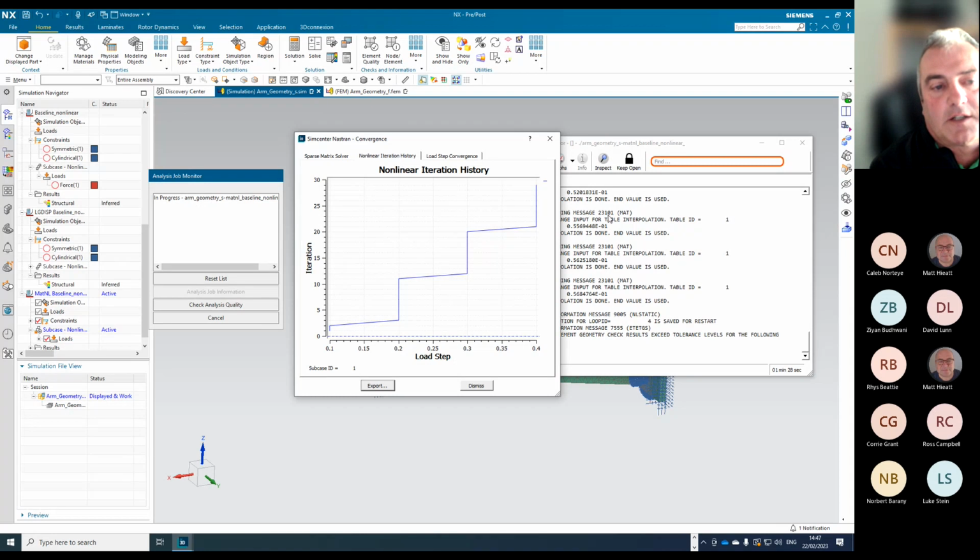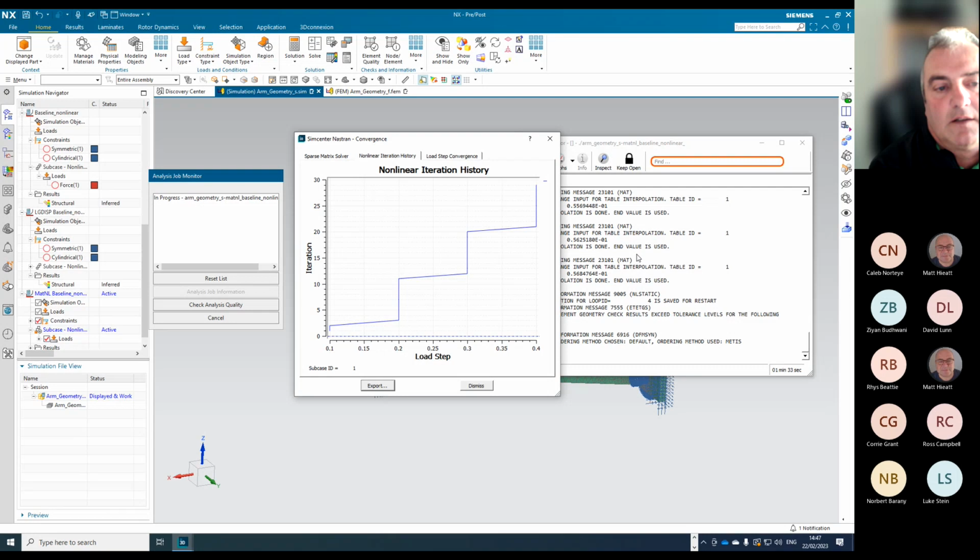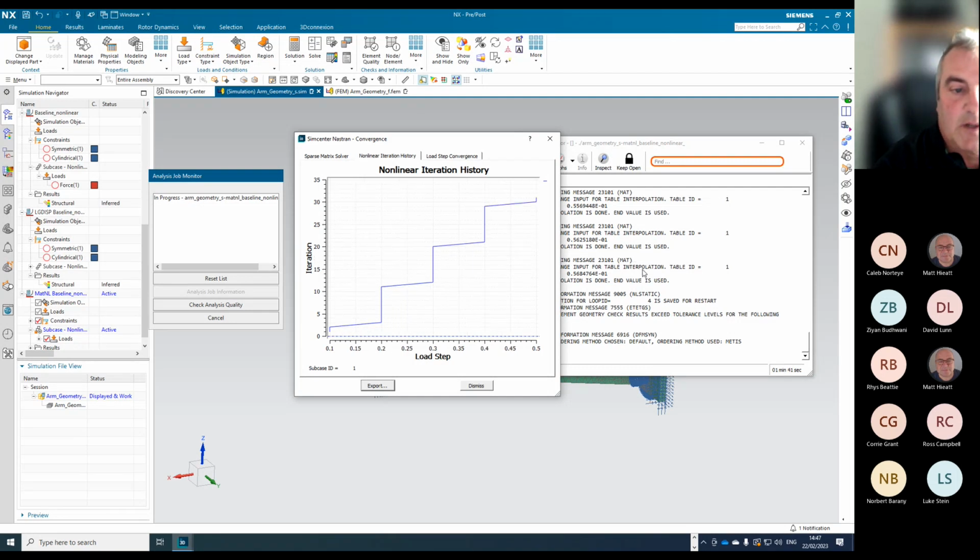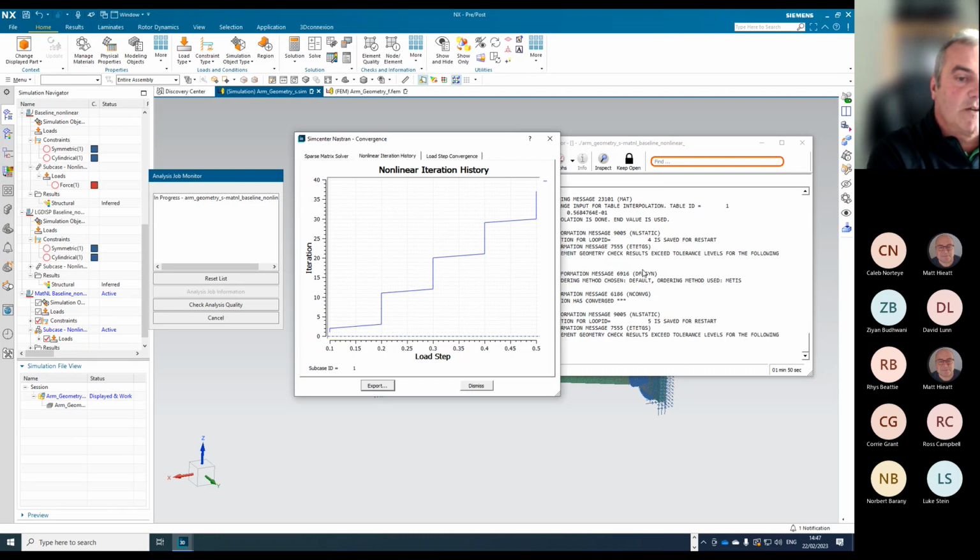Here it's saying you're outside the table, so we're interpolating, because here we've got very, very high stresses in certainly around the area we're fixing it. So it's just saying I had to extend the table and interpolate onto it. Again, this is an artificial example to show you the effects and how you might model them.